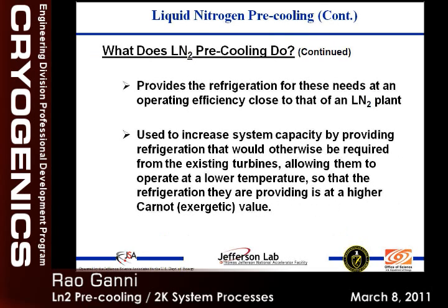And it provides a refrigerant. Also, the nitrogen plants, because they are commercial, large, big tonnage plants, don't throw away the turbine output. The turbine output is normally recovered in these nitrogen plants. The other thing is that because the specific heat ratio of nitrogen is 1.4 compared to 1.67 for helium, the heat of compression and the losses associated with it are less in a nitrogen compression process compared to helium. So the nitrogen plants tend to be more efficient than helium plants for the same range. Because of these advantages, production of nitrogen is normally more efficient.